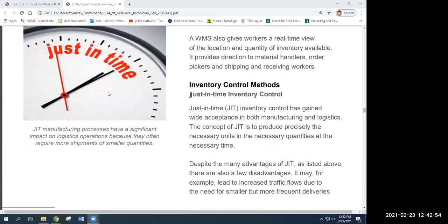So just in time, that is a very lean driven type of inventory, where let's say I'm making 50 engines today. And so I'm going to need 50 starters to put on those engines. My supplier for the starters shows up with the 50 starters before production lines that need it. And so I don't have to have any space dedicated for 500 starters or 1,000 starters. I know that there's a truck that's going to show up here prior to the shift, and those starters will be sitting right at the position where they're mounted to the engines.